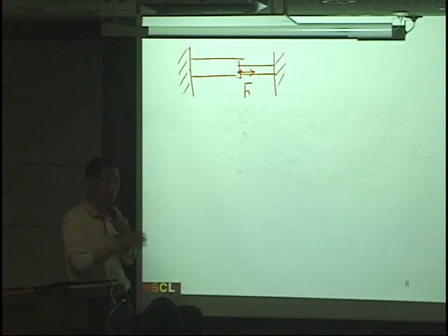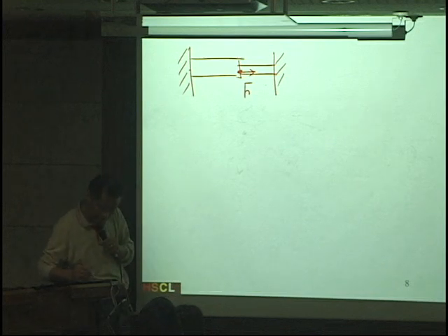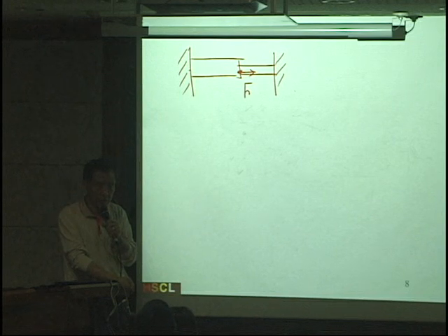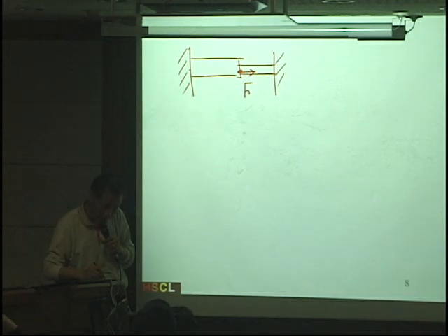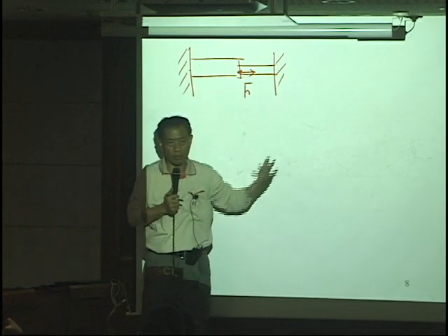This is one of really good examples, and this kind of problem will be one of the midterms. And is it statically indeterminate or determinate? That's right, this is statically indeterminate. Why is that? Because we would have 2 unknown reaction forces.